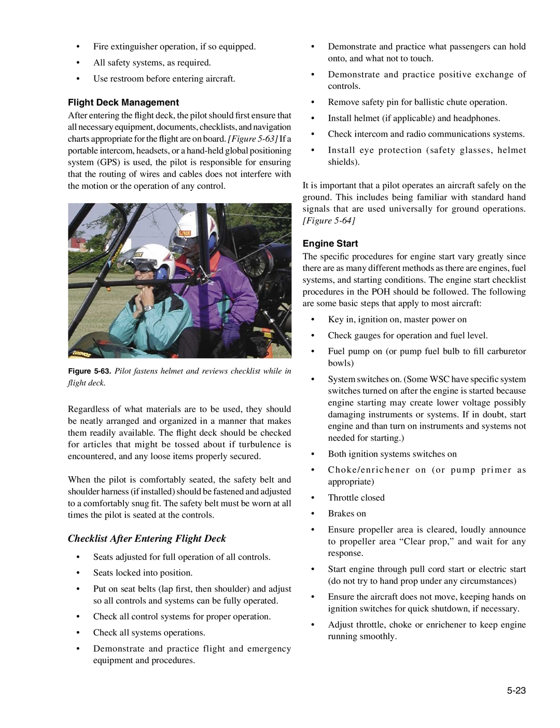Figure 564: engine start. The specific procedures for engine start vary greatly since there are as many different methods as there are engines, fuel systems, and starting conditions. The engine start checklist procedures in the POH should be followed. The following are some basic steps that apply to most aircraft. Key in, ignition on, master power on, check gauges for operation and fuel level.